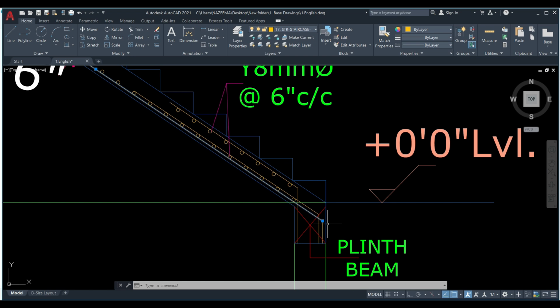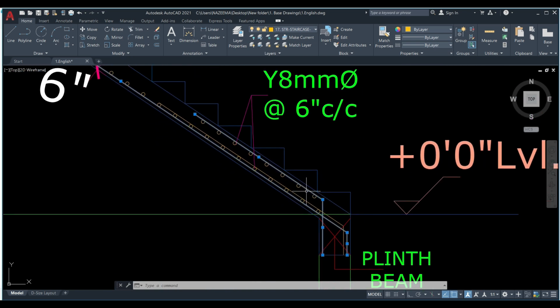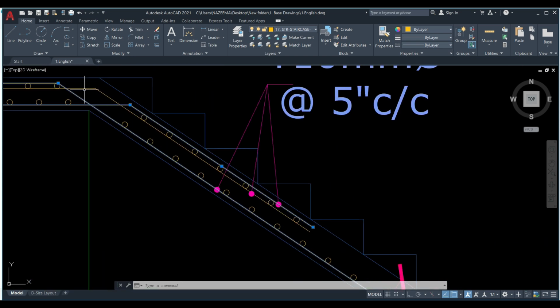When it comes to the bottom portion, the bar will just come and terminate over here. Okay, based on the bending moment requirement, you can have 1 more additional rebar like this that is going to come and terminate like this. Directly it will just come and settle inside. All right, now this is what is done in 99.9% of the cases. In some rare cases, what ends up happening is because of heavier moments, we end up providing additional rebars like this. Where do we do this? In commercial projects, where a lot of people are moving around and everything, in those projects, generally we provide one more layer of reinforcement like this.